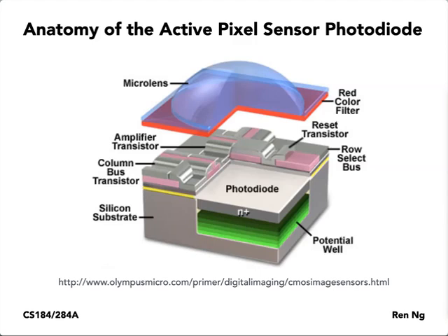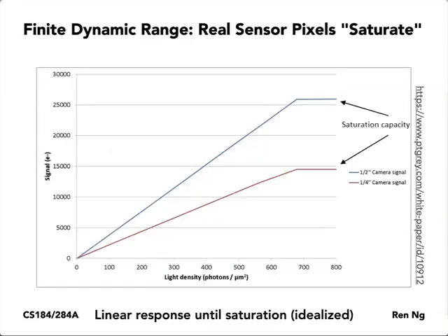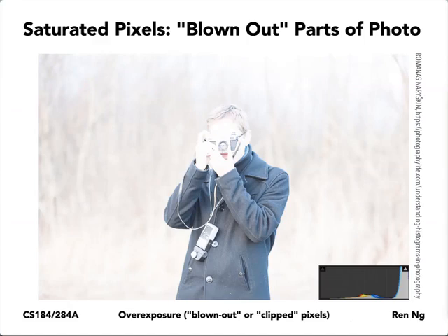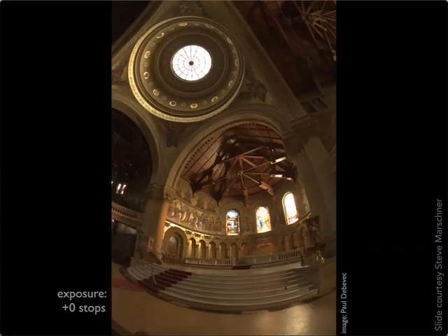They're going to max out at the number that this region can hold because the electric field due to the electrons will start to rise as that happens, right? The charge will increase and the repulsive forces will increase, that kind of thing. So the finite number in here is the thing that mostly dominates or causes the max pixel value in the saturation curve to occur. Okay, so that's the way to think about it. Okay, so again, this is blown out pixels.